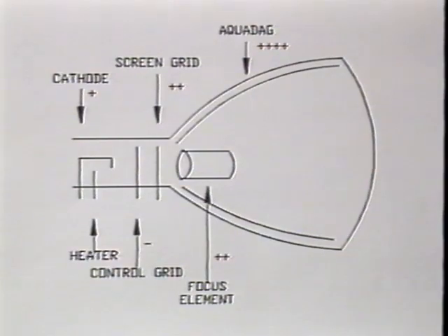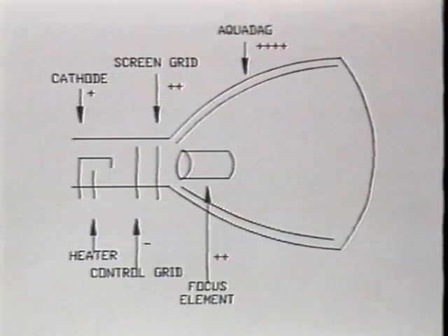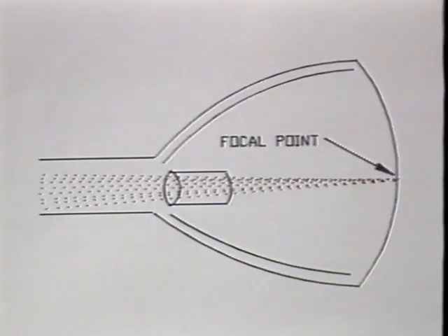This adjustment is also called the sub-brightness alignment. It may vary the cathode voltage or the bias of the output transistors. Align it so that the customer can select any brightness level from black to very bright with the external brightness control. After the sub-brightness level is set, you may move on to the focus adjustment.